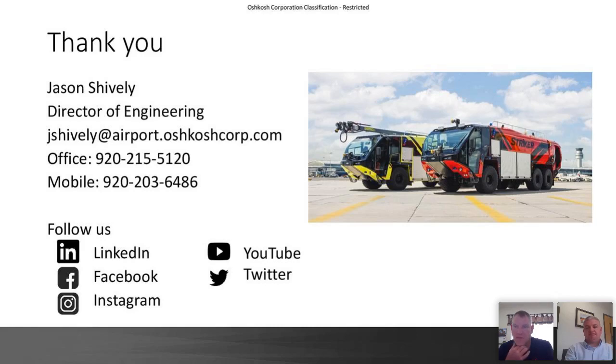That bleeds us into the next question. Is the water taken from the main tank or another reservoir? You just answered that one. Yep, it's from the main tank, just through the flush circuit. Any concern about cold climate? Trying to think if we've had a whole lot of that. I wouldn't expect to see any. Really, the viscosity of ARFF foam is about the same as water, and that really doesn't change a whole lot with temperature. So I wouldn't see that affecting the system.